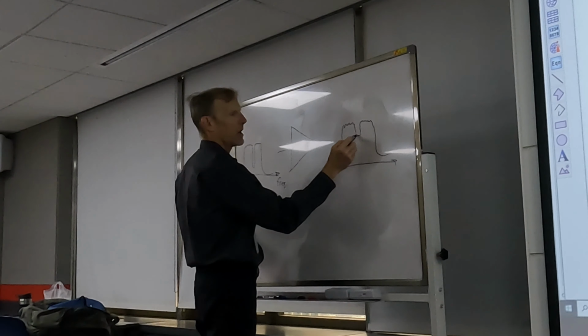And then you can also calculate error vector magnitude. We haven't talked about error vector magnitude at all today, but certainly you can calculate that from a noise power ratio signal. And the test signal in this case was a WLAN 11ax 160 megahertz signal with a notch added to it.